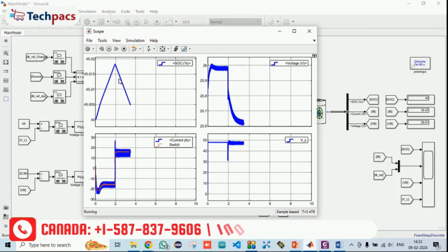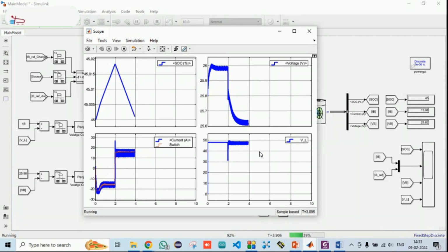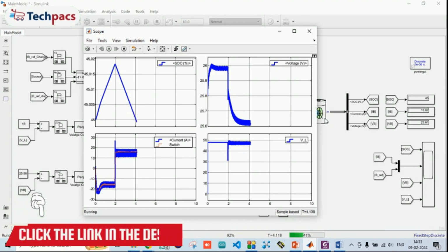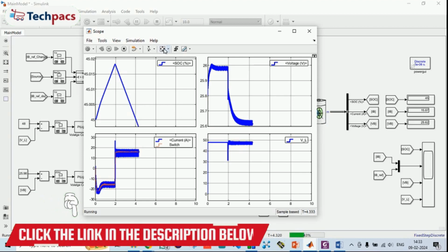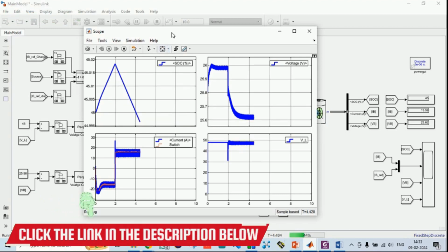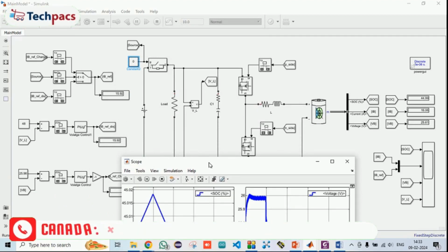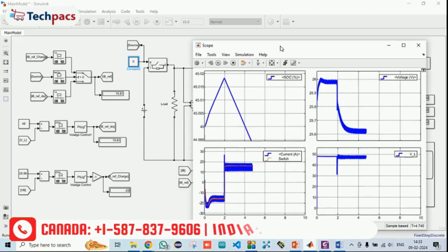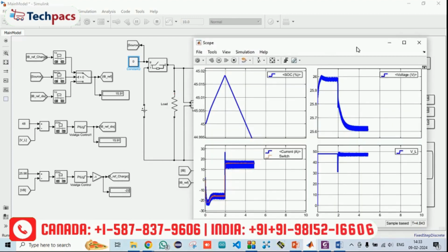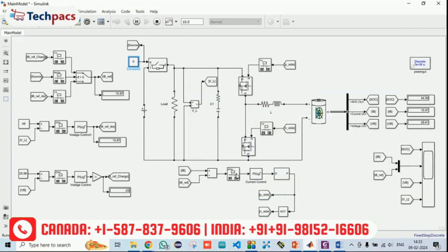The state of charge will be reducing because there is no input given to the power to get charged. Similarly the voltage will also reduce because the power available in the bus is discharging and is used by the load outside. So this is basically the system that we have designed, in which the same system will be capable of charging as well as discharging the bus system with the input given to them, and the decision is made using the PI controller.